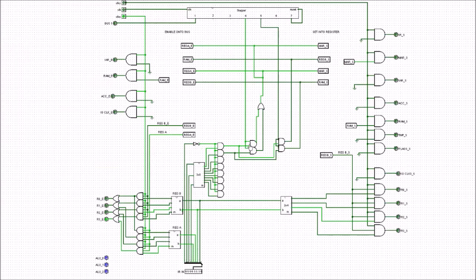So we're choosing this output here, and also this output here. We can see we're in step 4. That's gone high, that's gone high. We have our output gone high here, and again these here, so it's going to be Reg A enable and memory address register set.